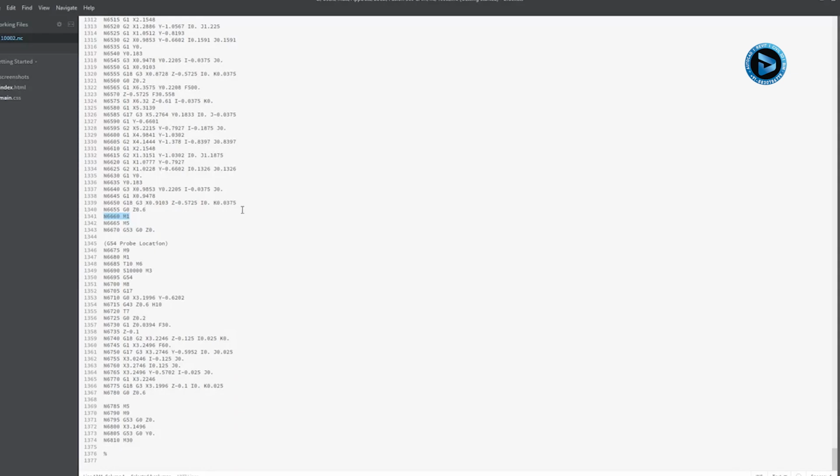When we're looking at code, the G code is generally going to relate to the motion of the tool in the machine and referencing things like canned cycles. The M codes will do things like turn the spindle on and off, decide which direction it's going, the speed of the spindle, and so on. For example, down here, we have tool 10 M6, which will have a tool change, and then we have M3.